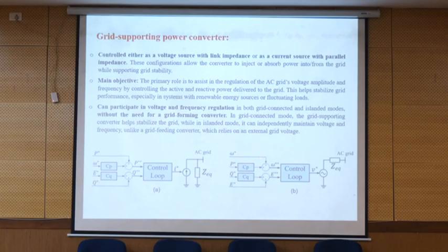Basically, this is based on the droop controller. Okay. So they said that delta frequency is equal to K or something times delta P, or delta P is equal to Cp times delta omega. So it means that when we have the changes delta F, so delta F is the frequency changes. So you have the reference in 50 hertz. So your reference frequency is constant, okay? But what you consider as a grid frequency is something different.